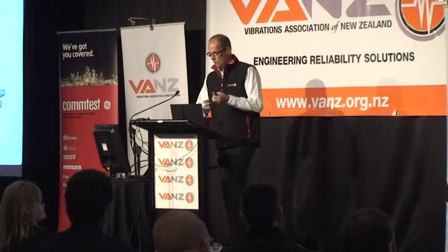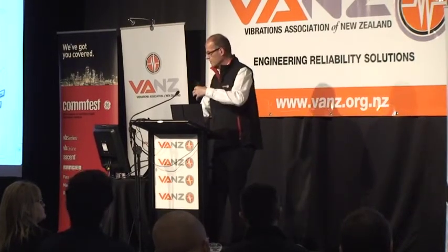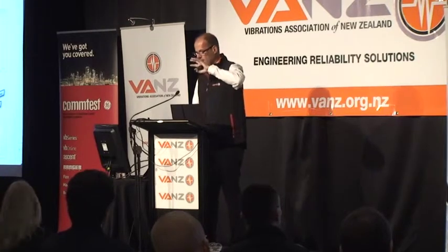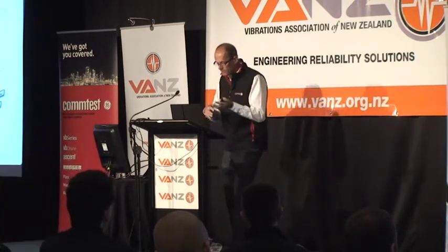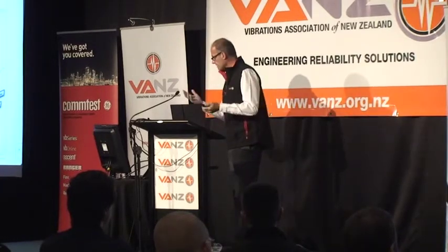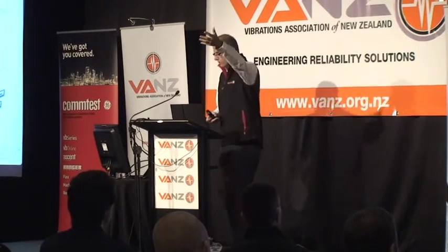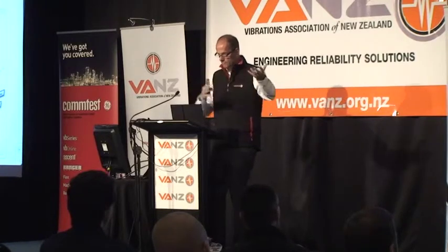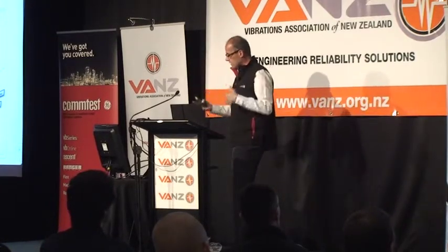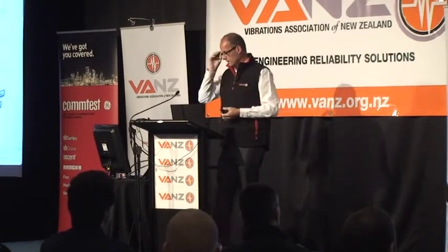Now, these little flags here, ultrasound, vibration, and so on, I put them in a certain order. It's not necessarily that with every fault condition, ultrasound will pick it up first, and infrared will pick it up last. For electrical, you'd use infrared. There are different types of failure modes and different types of equipment, so there are different condition monitoring technologies as a result.